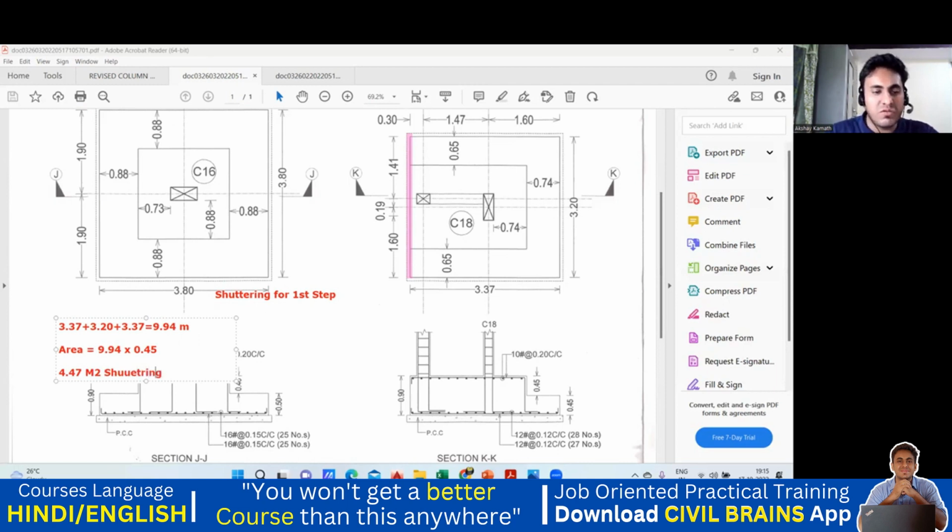So my first step of shuttering is done. Now come to the second step. Again, this length I know, this length also I know, and this length also I know. Add all three. Multiply by the depth of the second step, which is 0.45. Add both, and you'll get the total shuttering quantity required in this footing.